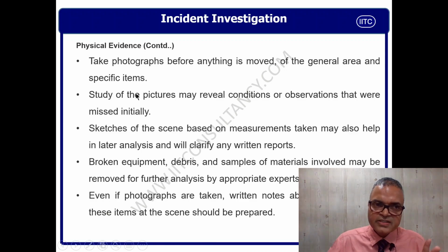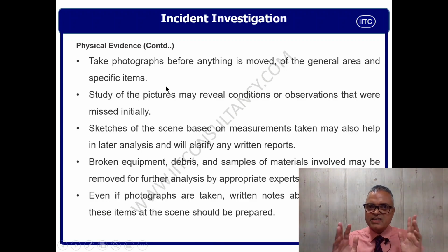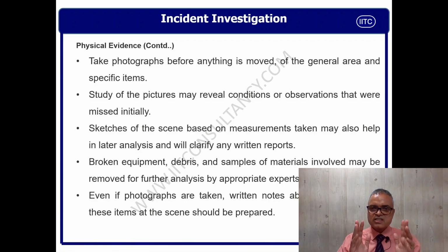For physical evidence, take the photograph before anything is moved, because if you don't, you will probably be misguided. Study of the pictures may reveal the real condition of the incident. Sketches of the scene based on measurements can also be useful in the later stage of the investigation. Broken equipment, debris, and samples of material involved in the incident should not be removed. They must be analyzed to identify the right root cause.